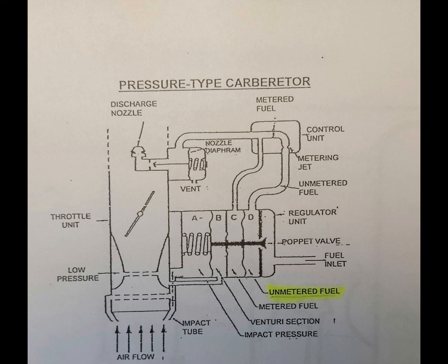What is the purpose of filling a pressure injection carburetor full of fuel and allowing it to soak for a period of about 8 hours prior to installation? To soften the diaphragms.